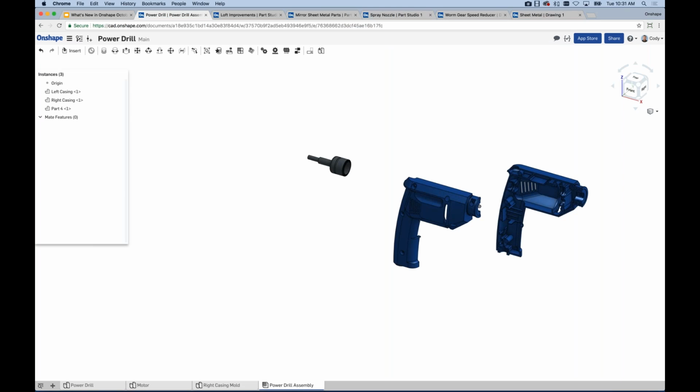This sounds like a trivial thing, but it could be a really big thing if you spend a lot of time inserting parts. And there are a lot of users out there that have even gone through the level of, I insert and mate the parts in a single shot using snap mode and mate connectors. And, in that case, the insert dialog is up the entire time I'm inserting parts. And I certainly don't want accidentally hitting the red X to cause me to lose all of that work. Right? So that's the idea behind the restore.